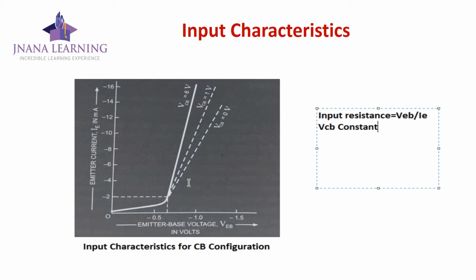Another thing we have to know from the characteristic curves is that as the collector base voltage increases from one value to another, the conduction gets better. Why? Because a large collector base voltage causes the depletion layer at the collector base junction to penetrate deep into the base, which reduces the resistance between the emitter base and collector base region. So as the value increases from 0 volt, then 1 volt to 6 volt, the conduction is better.